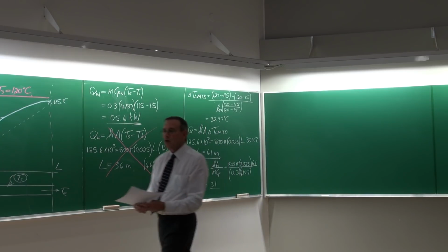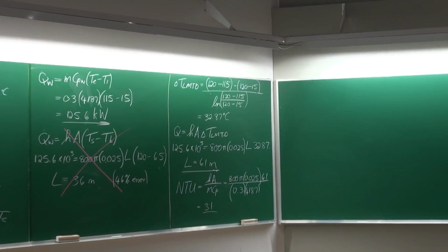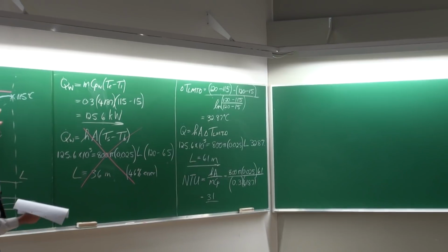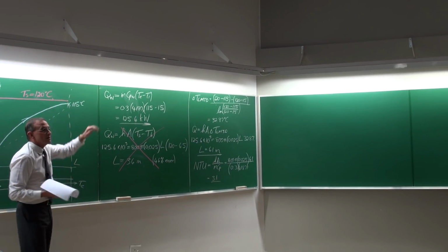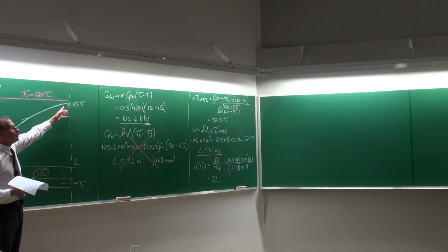So it is already on the upper limit of a good design. Actually, you could decrease the length maybe to 3 or lower, but it's already a very high outlet temperature to reach when you get to 5 degrees. Normally, a good rule of thumb for heat exchangers is 10 degrees.